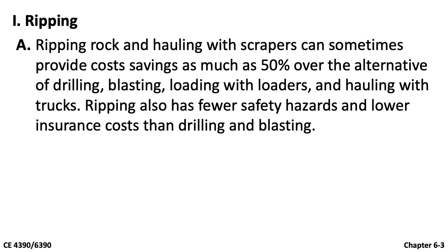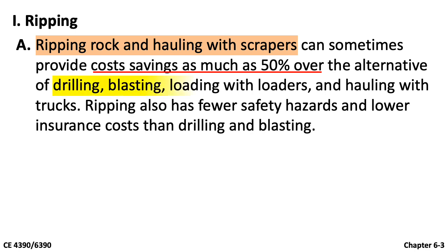Ripping rock and hauling with scrapers can sometimes provide cost savings as much as 50% over the alternative of drilling, blasting, loading with loaders, and hauling with trucks. Ripping also has fewer safety hazards and lower insurance costs than drilling and blasting.